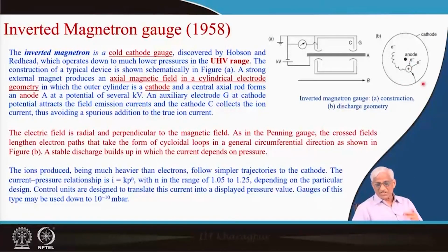So, this cross connection of these things with an extra electrode has created a very good measurement down to 10⁻⁸ torr in inverted magnetron gauge. Beyond that, I can keep on explaining these things, but I think if you go to the internet, you will get very good, very long explanation with lots of derivations and all. Since lack of time, I will not be able to explain that, but this gauge is quite popular, and several versions of this gauge are being developed by several companies.